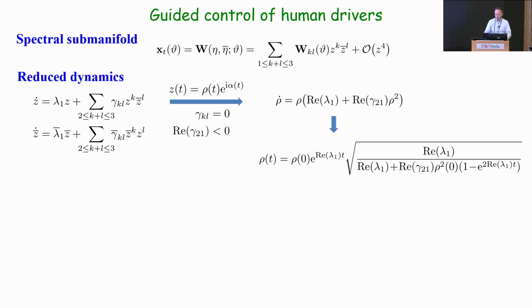Second thing is, if you actually solve this nonlinear equation, which actually can be solved, right? This is so simple analytically, then you actually can show that this actually decays faster than the linear counterpart. Okay? So you take the nonlinearities, which in some sense used to be your enemies because it gave you a difficult control problem to design, and you make it your friends because by designing a right nonlinear controller, actually you can make the system to attract faster.